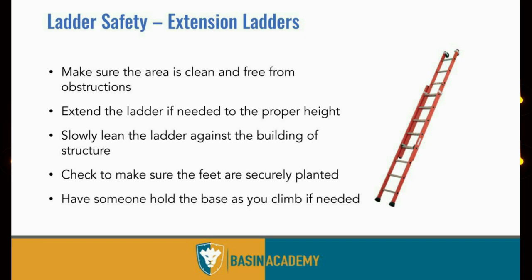Make sure the ladder is clean and free from obstructions. Extend the ladder if needed to the proper height. Slowly lean the ladder against the building or structure. Check to make sure the feet are securely planted. Have someone hold the base as you climb if needed.